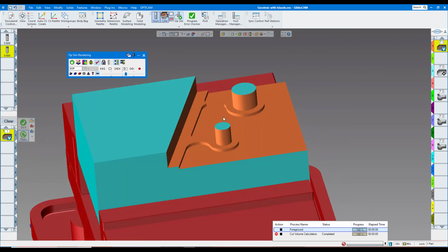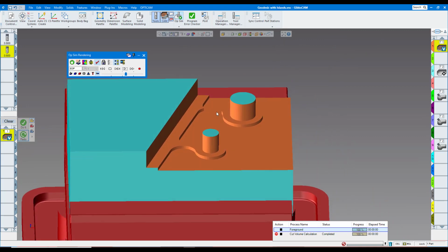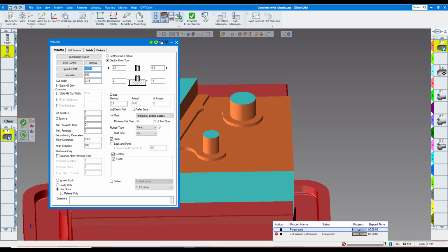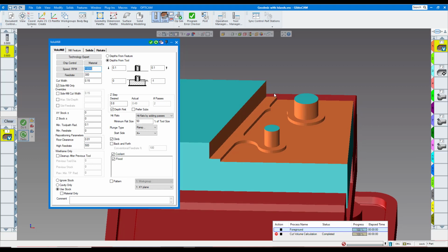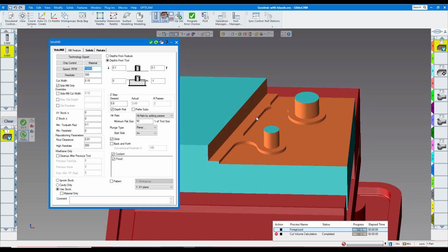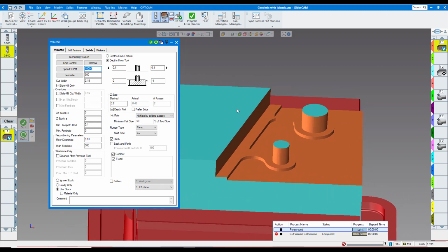And you can see it took about 800 thou steps there, at least this step here, and then it kind of cleaned up here. And the reason it cleaned up here is because I have hit flats after adding passes. So it went down because it was an inch depth from the top to here. So 800 thou, it's going to do that, then it's going to hit the flats. But ideally this is not the best because when the ball end mill comes back, it has too large of a wall there to use the ball end mill. You would have a difficult time machining that.